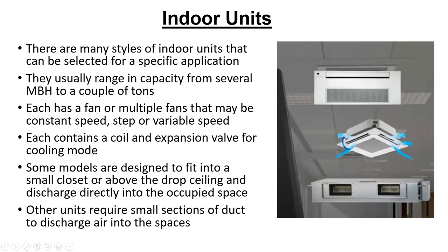So like these guys on the bottom, this would go, say, above a drop ceiling or maybe in some sort of a closet, and then you'd have to run a little bit of duct work to get to some diffusers to distribute the air. These cassettes set in the drop ceiling, and these guys just set high on the wall. This is what you see sometimes in the motel rooms and that sort of thing.